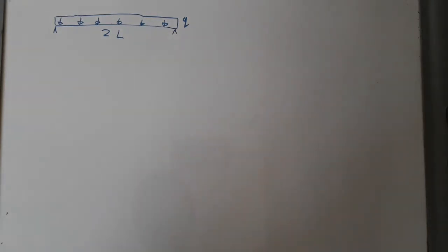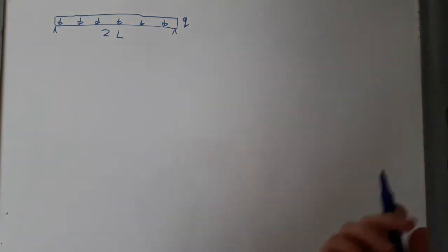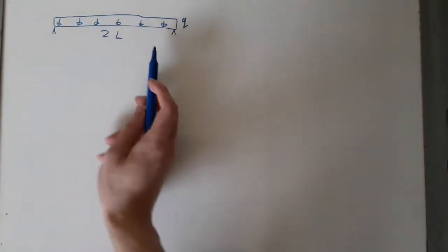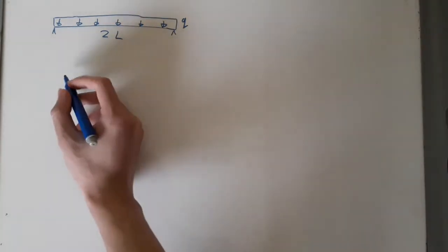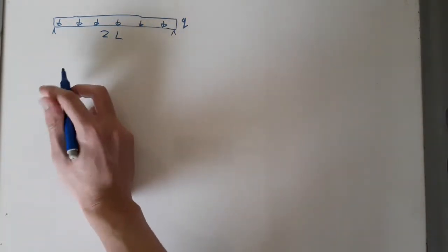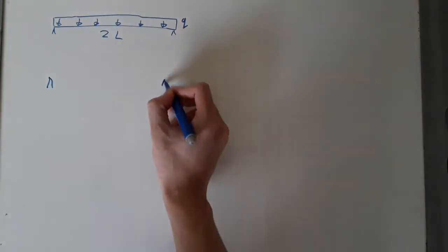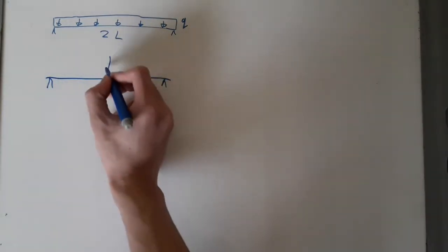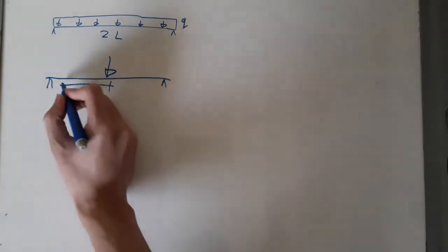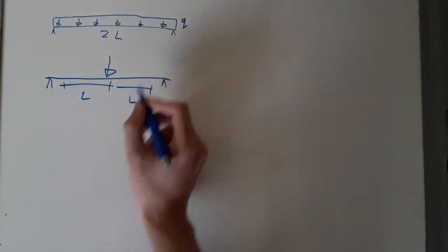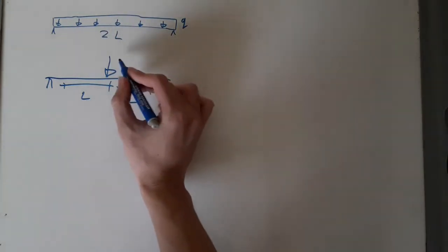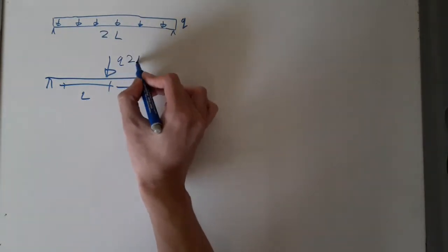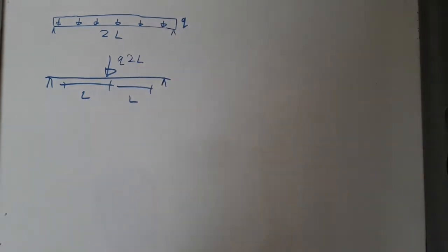Okay, so this is going to be a quick little video on how to do work equivalent loads. First off, in the simplest scenario, let's say we have a beam of length 2L with a distributed load of Q. Normally, what we've learned previously in strengths classes is that the equivalent of this would simply be a force acting at the midspan with a force equal to this equivalent loading. So that would be Q times 2L, the length times the distributed load.